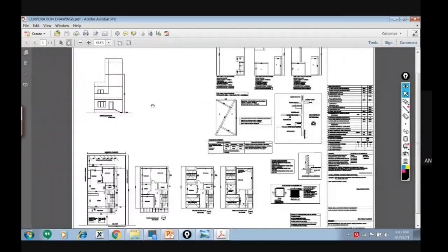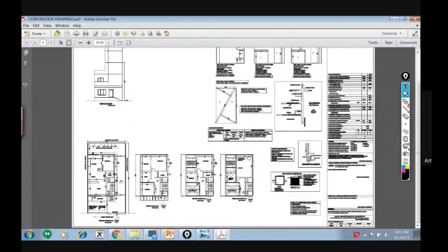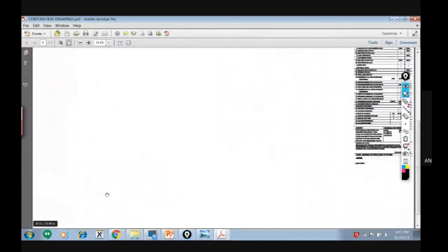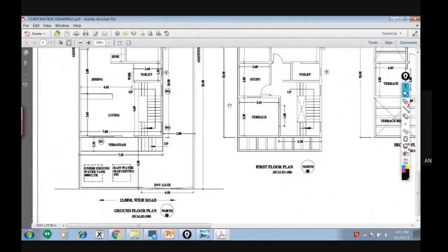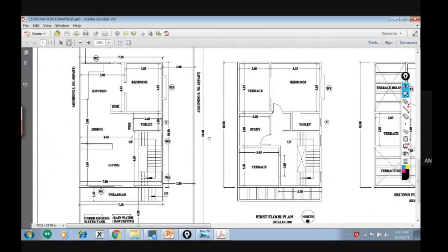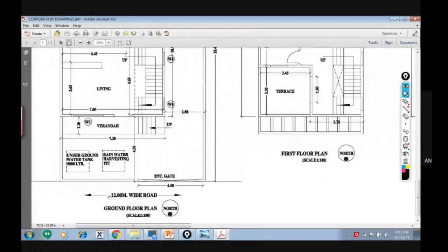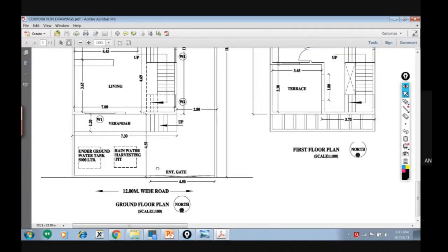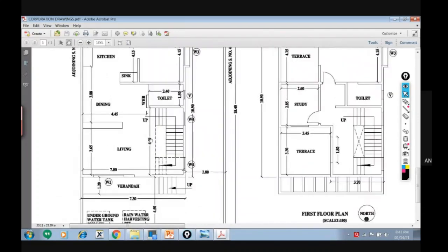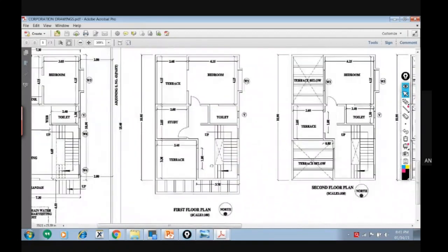Have you seen any submission drawing, architectural submission drawing previously? Yes, sir. Now you should actually read different drawings. So submission drawing is different. Working architectural drawing is different. And different objects are there, different things are there. Let's say this is a submission drawing of an architect where there is a ground floor. He has written the scale as 1:100. Then they give the marking of the north side. Then these are the dotted lines, then dimensions are given, then rooms, setback distances,